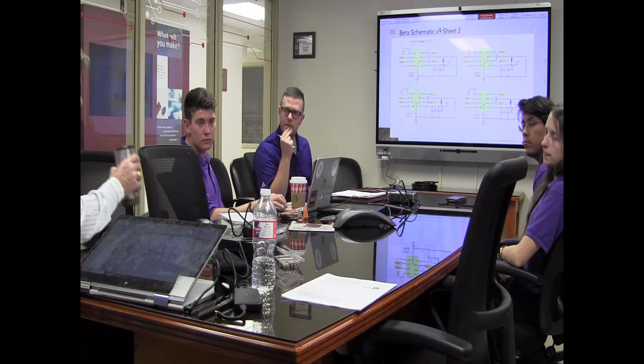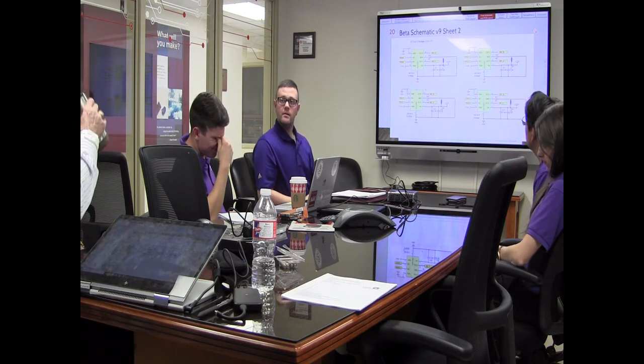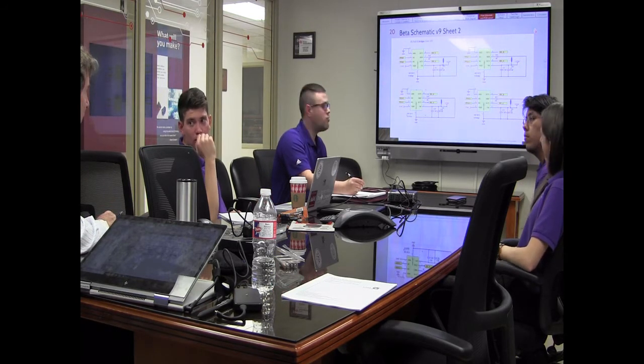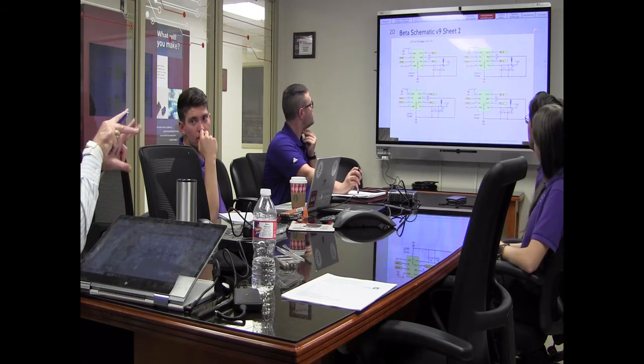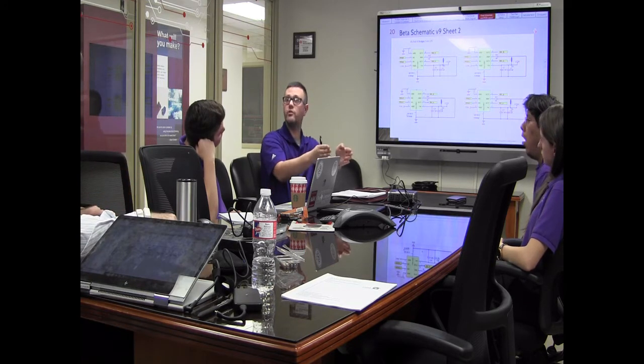Do those H bridges have shoot-through protection? That's a good question. I don't remember. If I were to screw up on the first one and take PWM 8 and 9 and put them both high, I could end up with a situation where through my H bridge I'm shorting VCC to ground, which would I think be somewhat undesirable. Exactly. But I think you have IN1 and IN2. Those are controlling the 2 different outputs, right? No, you're right, you're right. Okay. You're right.